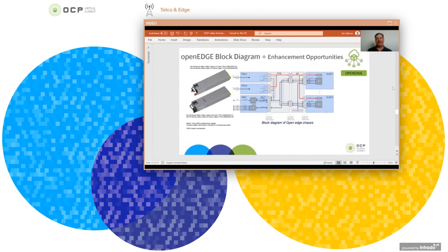However, if there's something downstream where some of the lower voltage rails go into the sleds, you could have something that's actually a condition that would normally be considered a fault. But if the 12 volts looks like it's being presented well to the PDB, the system could think that everything is fine. So by having intelligent DC to DC converters directly on the PDB, there could be additional information to say that everything is just fine for the sled as well.